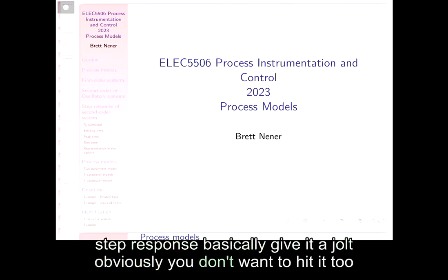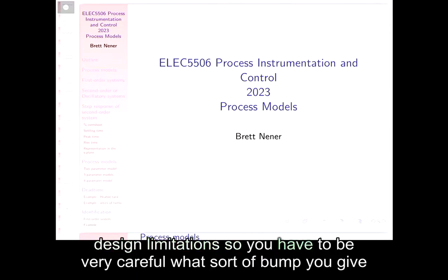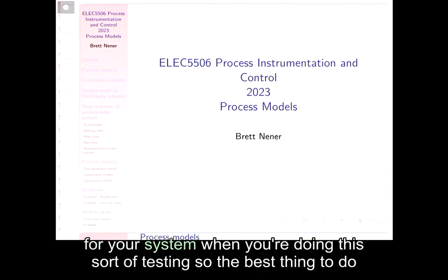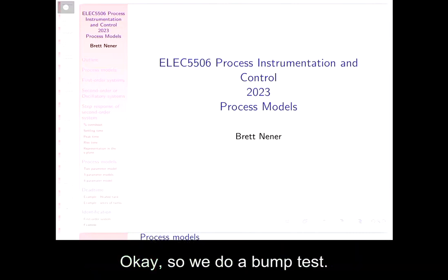Give it a jolt. Obviously, you don't want to hit it too hard because you might put it into an unstable state or you may exceed its design limitation, right? So you have to be very careful what sort of bump you give to your system when you're doing this sort of testing. So the best thing to do is talk to the technicians, and they'll give you a pretty good idea of what you can do with the system. Okay, so we do a bump test.